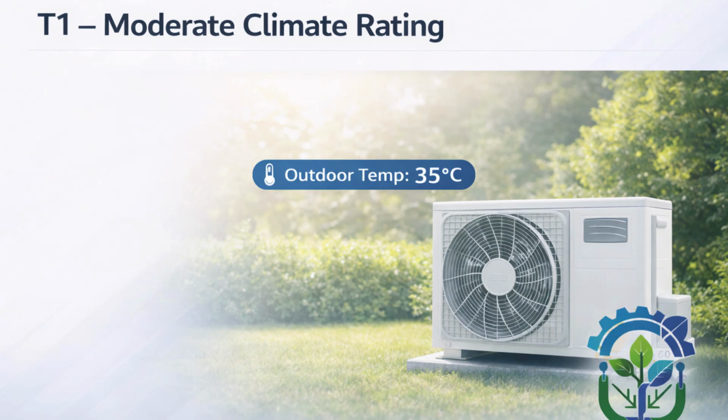Talking about T1, which is the moderate climate rating. T1 represents moderate climates. The standard outdoor temperature for T1 is 35 degrees Celsius. This is suitable for Europe, mild climates, and controlled environments. At 35 degrees Celsius, condenser pressure is low, the compressor works comfortably, and efficiency looks excellent. This is why T1 equipment often looks very attractive in catalogs.